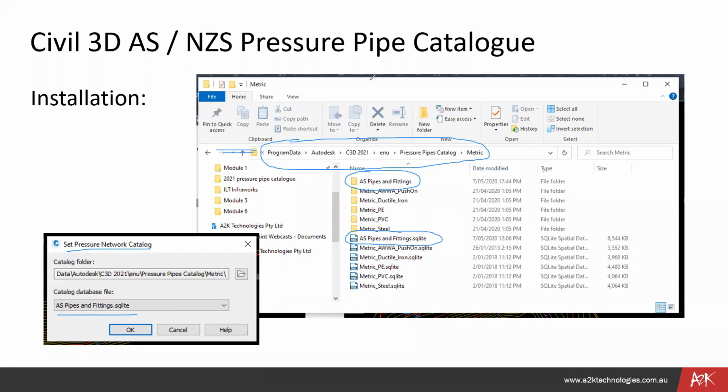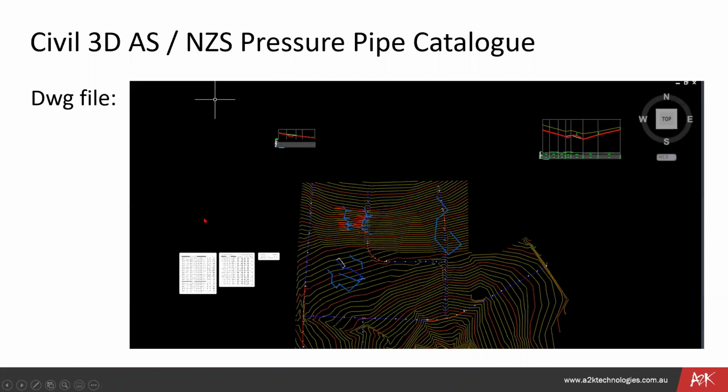All right, so let's continue on, clear my drawings and close that. I will also give you, when you ask for the catalog, this drawing. I have some table styles set up, some label styles, and most importantly, the long section band styles. I've got a whole bunch of those for you to use, similar to what you get in the ANZ country kit. These are just starter styles that you can then modify for your own template as to how your particular company standard wants to see those produced, but they're all there for you. You don't have to start from scratch.